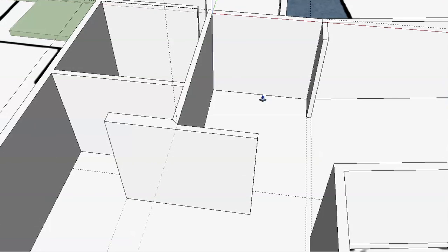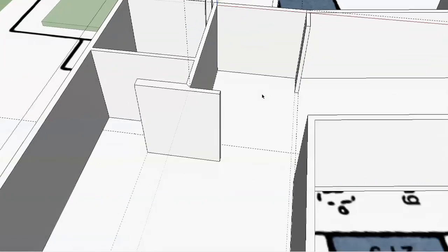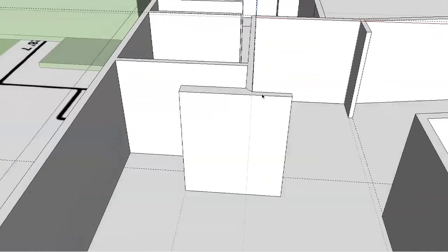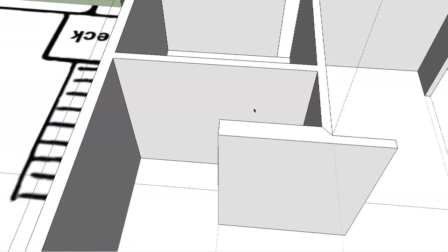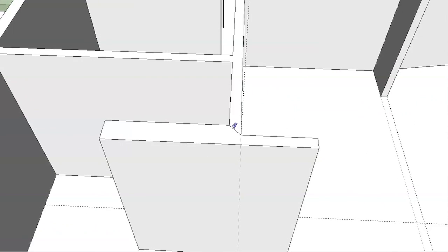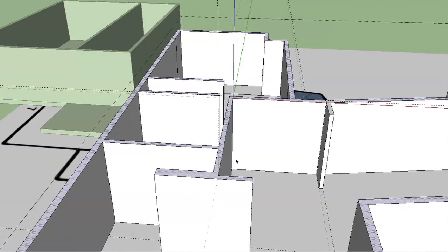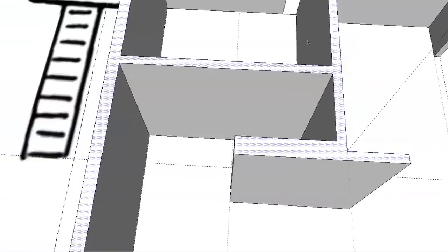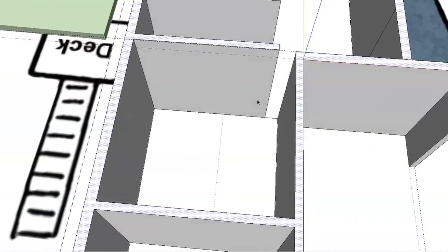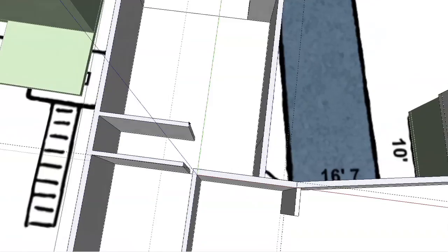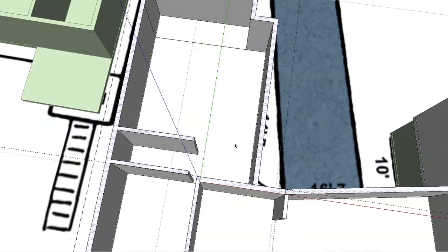I'm going to do 28 inches. There we go. And now that wall is looking a lot more like it does in the photo. And we've got a nice little alcove right here. We've got a little extra line right here that I'm going to erase. That way we keep the tops of all our walls pretty seamless. Now, we know that we're going to have a doorway right here. That's going to lead into the bathroom. But now we've got some strange things going on with our walls in this bedroom area. So what are we going to do to fix that?